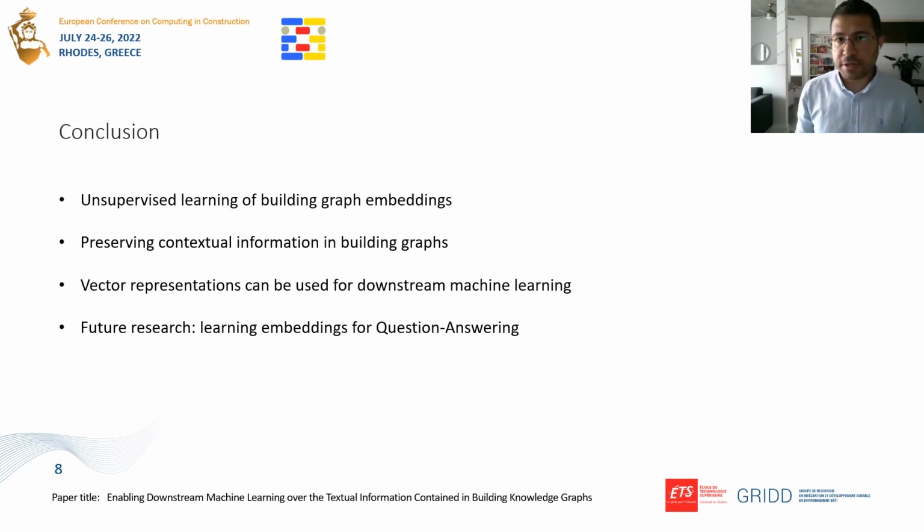Currently, we are experimenting with this approach to map natural language statements into corresponding facts contained in building graphs so we can assist non-technical users to perform natural language queries over complex building models.